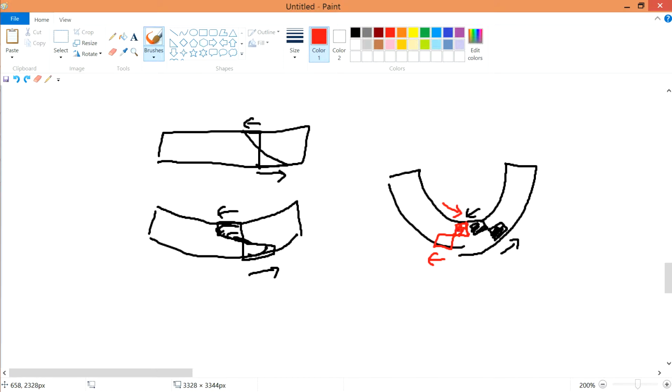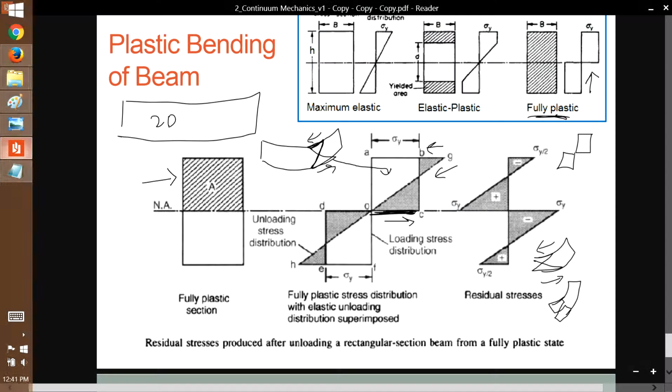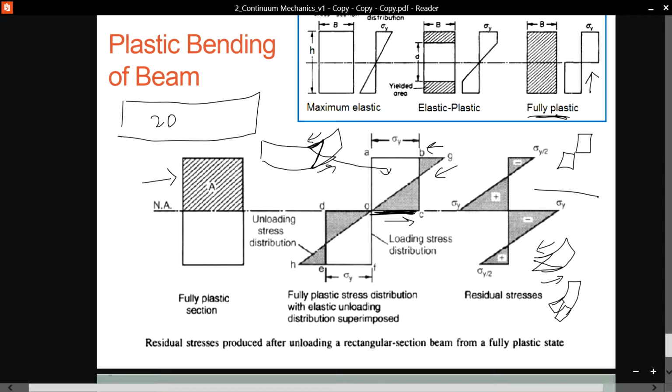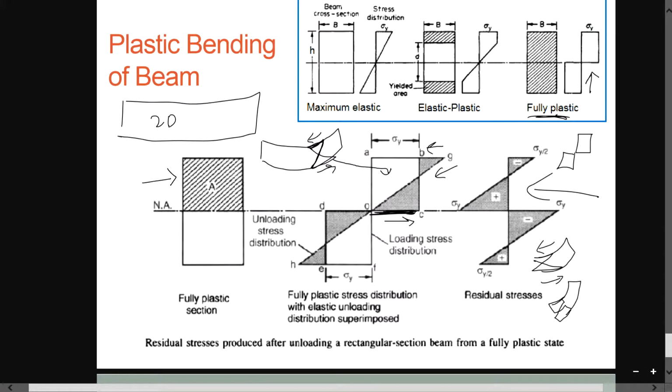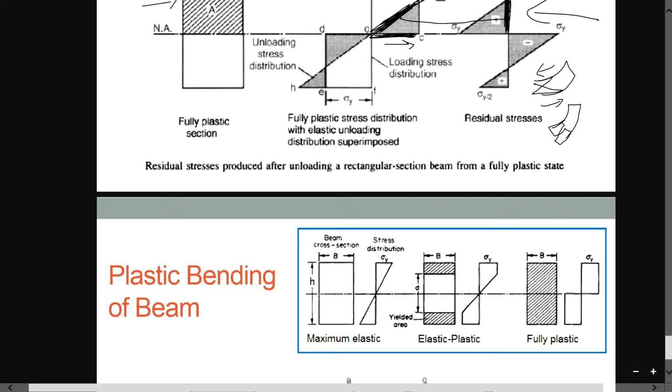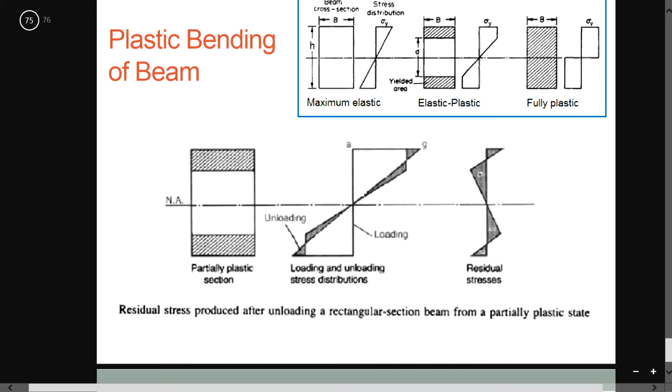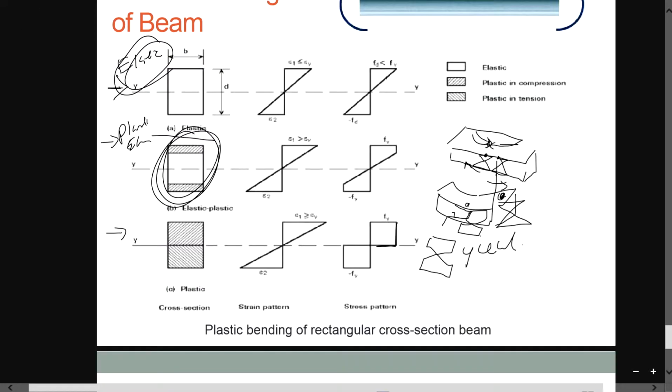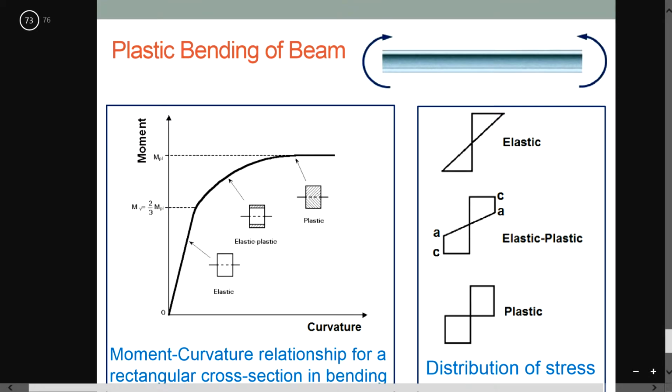If you continue to do this, you plot out all the stuff over here. But if you apply this particular stress and then release, the residual stress is over here. Take note that it is drawn with a similar shift, but this part will be plotted over at this side, while that part will be plotted over at that side, based on the switching. This is, to my best knowledge, the understanding of the plastic bending of a beam.